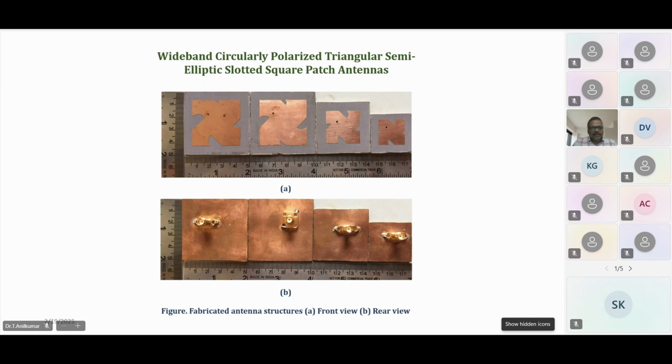Next. So see, in the first one all the areas of the slots are different, and in the second one opposite areas are equal. I have named them ASP1 and ASP2, ASP3 and ASP4. ASP3 and ASP4 are scaled down antennas, because I tested this particular structure scaled down in order to get higher frequency. Since f is inversely proportional to lambda, if the wavelength is reduced, the frequency is going to be increased, so this design has worked at higher frequencies also, right?